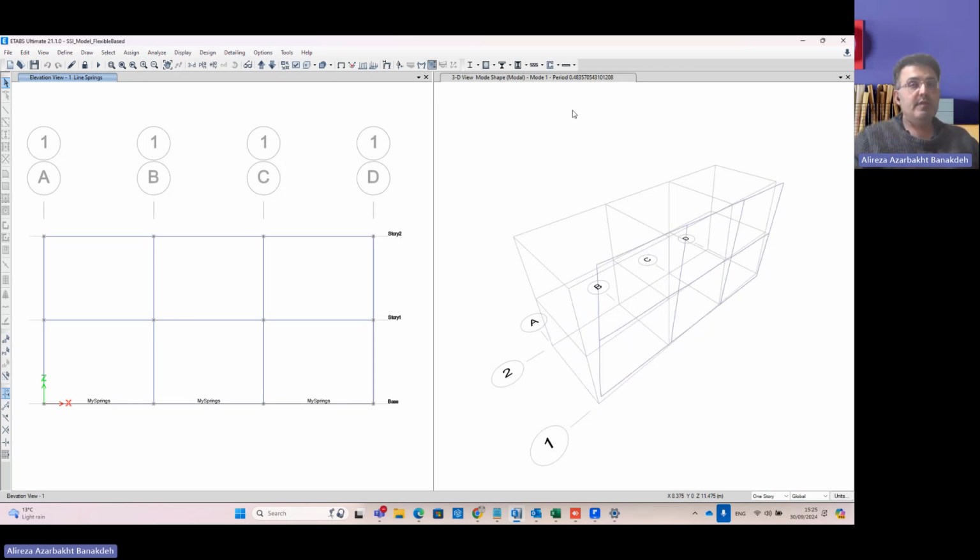So today we are not going to the design phases, but when you go to design phases, because the soil foundation structure model has a more flexible kind of stiffness and higher natural period, usually, not always, it's on the conservative side if you consider the fixed base assumption model to design your structure.